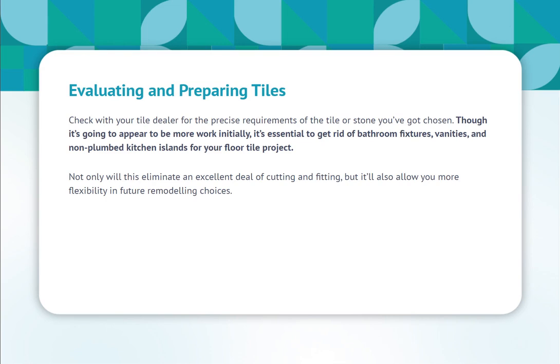Though it may seem like more work initially, it's essential to remove bathroom fixtures, vanities, and non-plumbed kitchen islands for your floor tile project. Not only will this eliminate a great deal of cutting and fitting, but it will also allow you more flexibility and future remodeling choices.